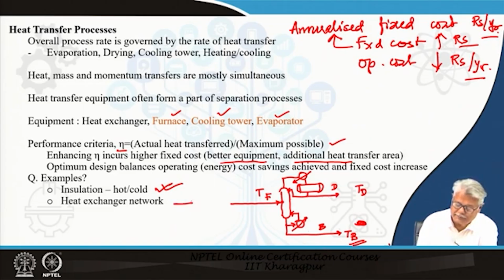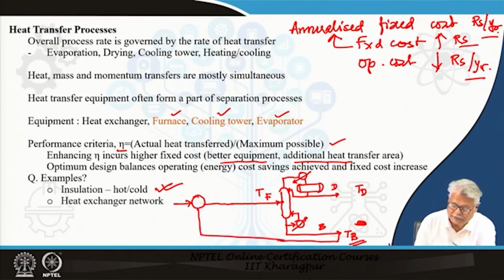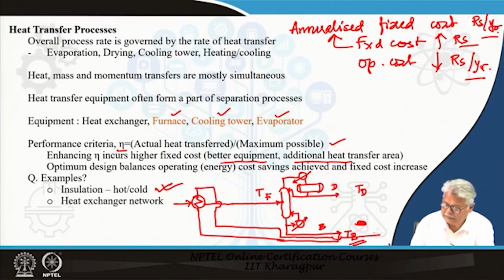So, it is possible for me to put a heat exchanger here by investing something definitely, take this stream, preheat my feed, and then send it out as bottoms.